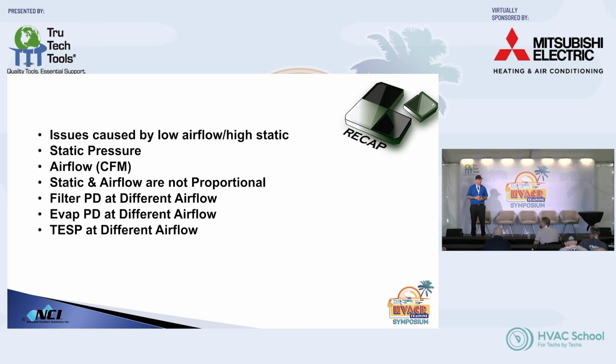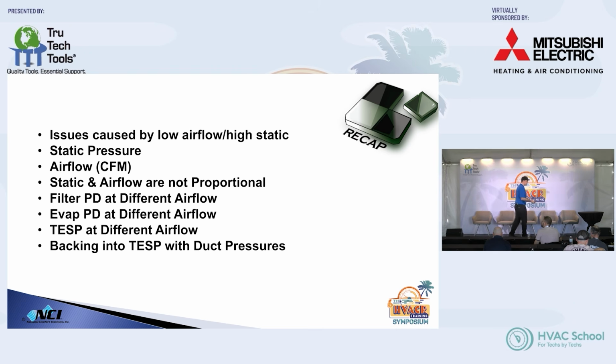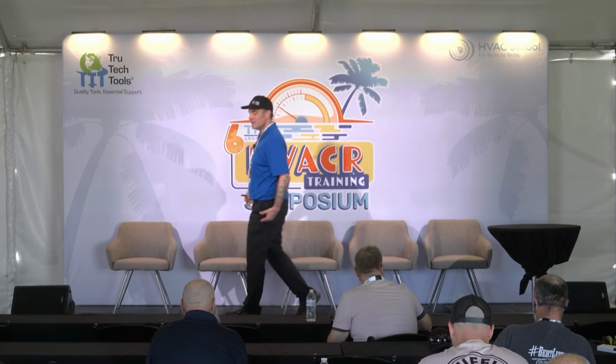Total external static pressure at different airflows, right? And then the biggest one, backing into a TSP with duct pressures. That's my favorite thing. I would spend the time to do that, and that really changed the outcome of my installs. I would have a hard time sleeping at night when I installed a system and it sounded like a rocket ship. I just felt defeated, right?